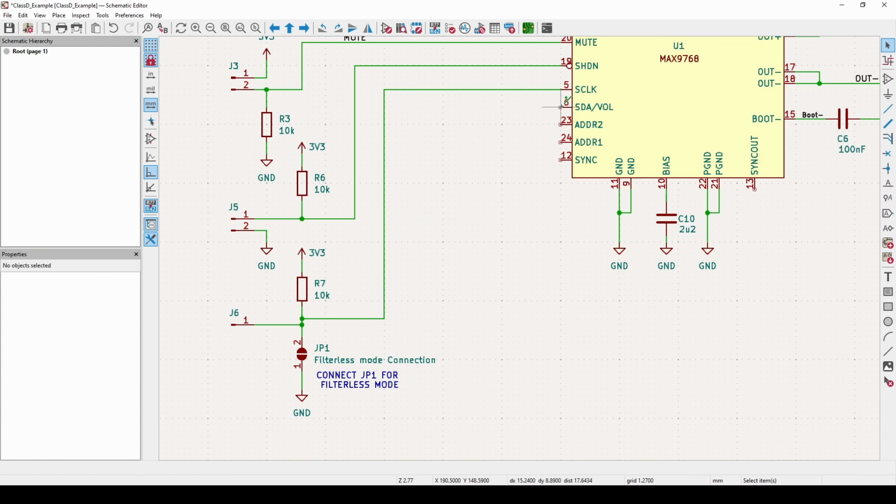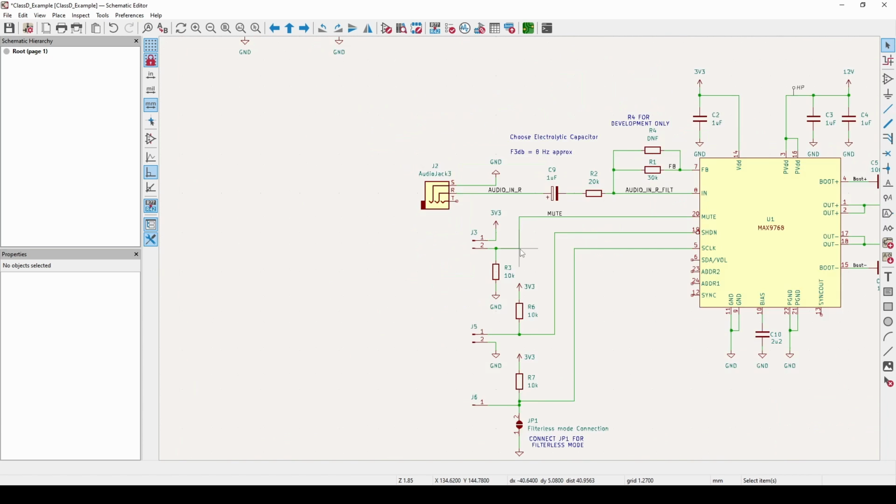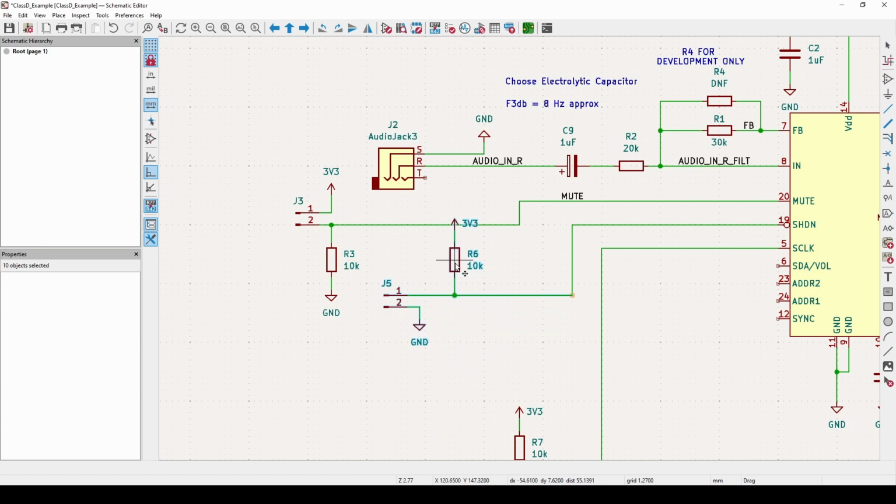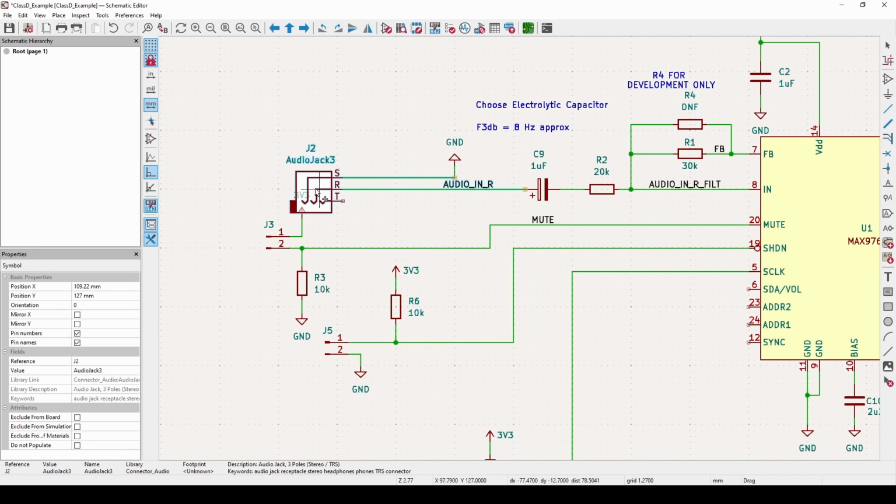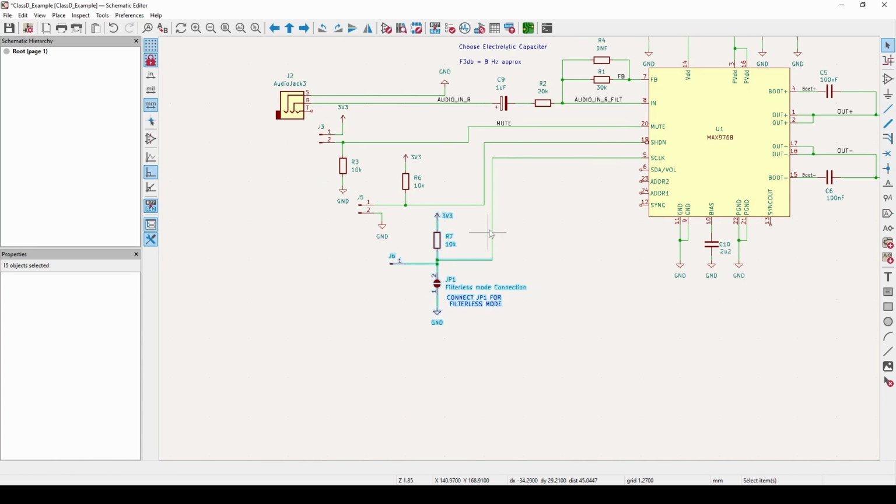Now, if I don't have a microcontroller, basically the volume needs to be controlled with a variable resistor, which would connect to this pin over here. So I'm going to bring this pin out. Similar to what I've done over here, I need to connect one node to a 10 kilo ohm resistor. And that's if I'm going to be using a microcontroller to ever control the volume on this, or I connect that to a variable resistor. So that will require a three-way jumper pad.